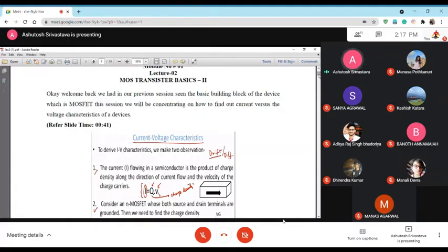Knowing very well that the MOSFET transistor essentially is a four-terminal device. There are different types of junction formations, including metal semiconductor, metal insulator semiconductor, P plus N, and so on and so forth. And if you are trying to achieve very advanced kinds of transistors, then you can have heterojunctions, homojunctions, or semiconductor p-i-n junctions.